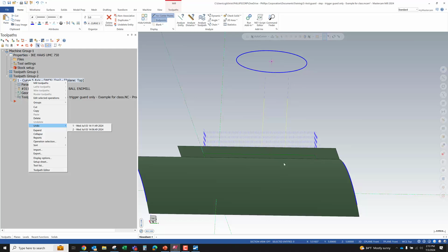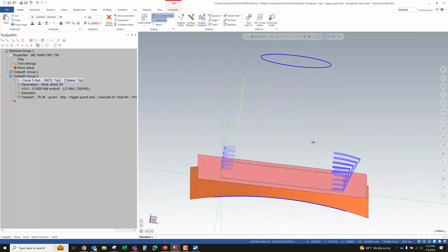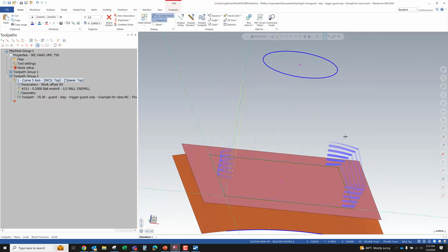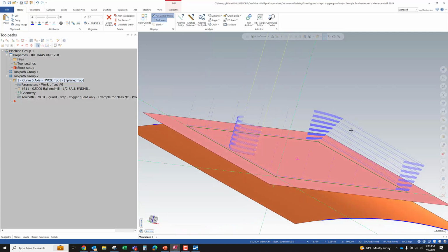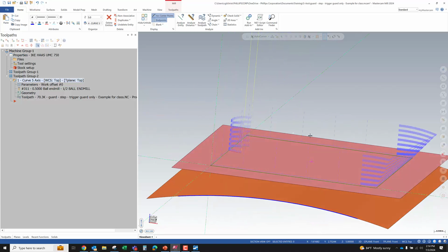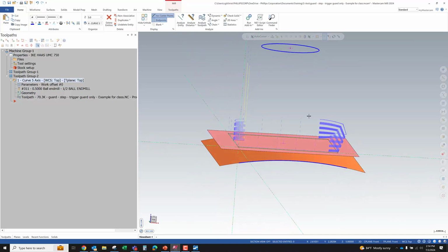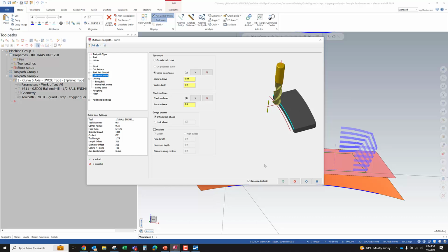It's just so hard to say sometimes which particular change resulted in this part of the toolpath being fixed. We did add that extra line, but even after adding it, I still thought I saw a portion of the vectors near the transition corner that looked funky, like there was that weird kink in the toolpath. So all fun stuff to explore with learning 5-axis for Mastercam curve 5-axis toolpath.